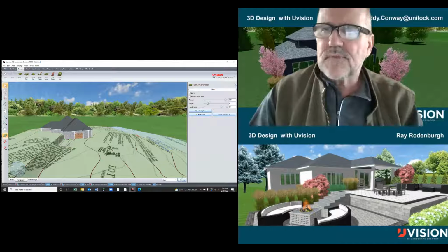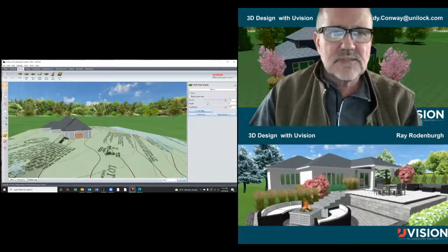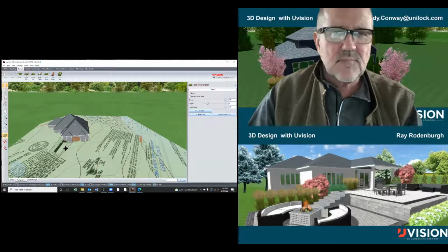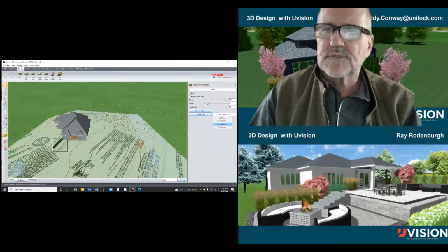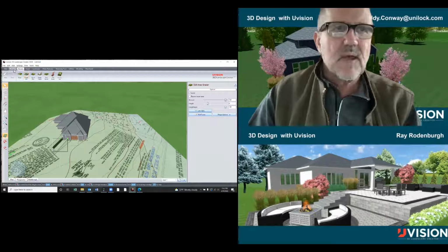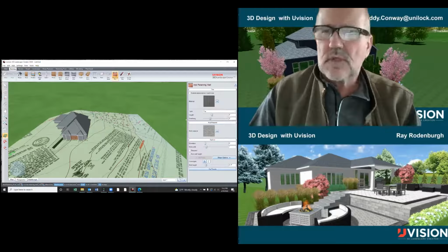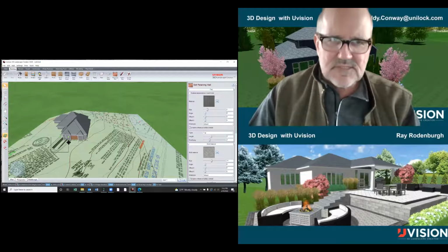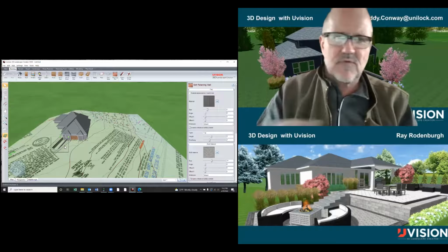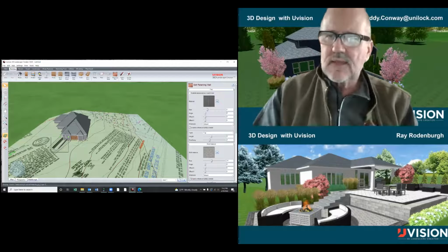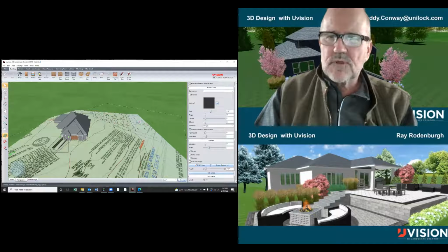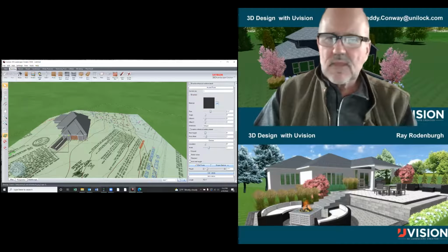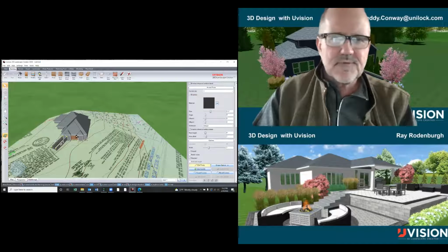I could go to this button here, give me a nice, I'm just going to push that in a little bit. So then I go shape options, copy shape, building, retaining wall, shape options, paste shape. There's my wall. I can cut this wall out just by stepping down. We've done this in the other classes. And I'll raise the one at the back to fit. Edit points, stepped.